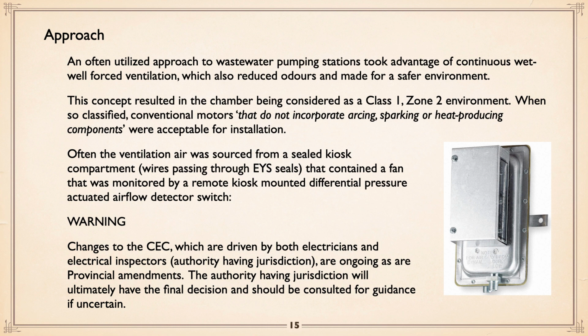Okay? And at one time, in class 1 zone 2, conventional motors were acceptable as long as they did not incorporate arcing, sparking, or heat producing components. And believe it or not, a standard open drip proof motor met that requirement.